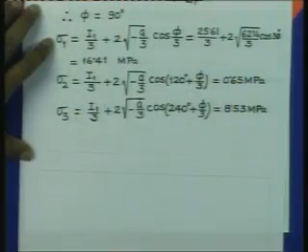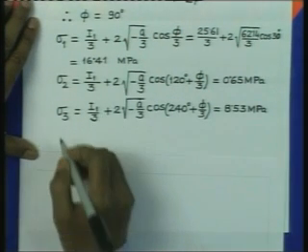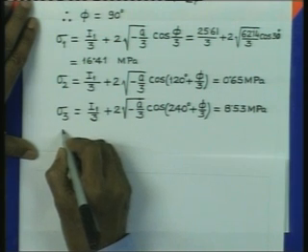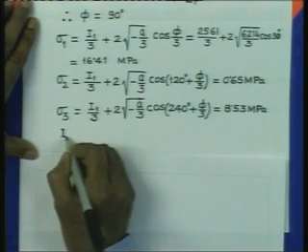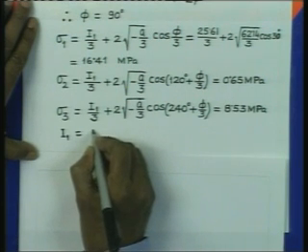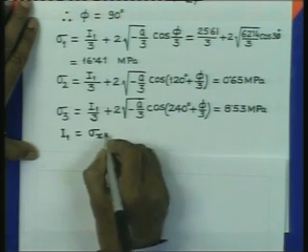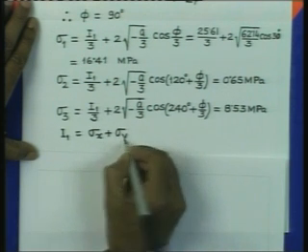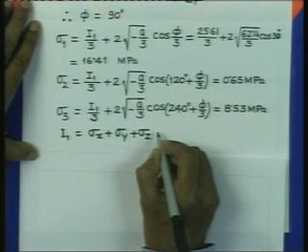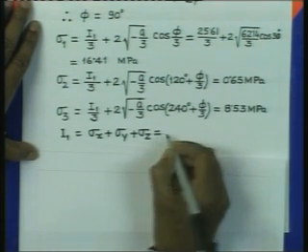Now, at this point itself, I would like to tell you that sigma 3 can be calculated in a slightly different way, since we have the stress invariant I1. This I1 is given by sigma x plus sigma y plus sigma z, and it can also be equal to the sum of the three principal stresses.